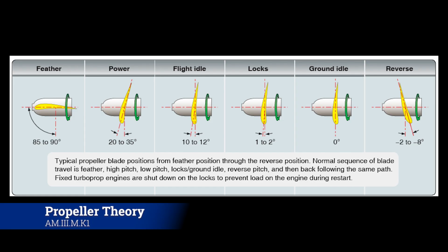C-130s are another really good one to watch. You can watch videos of these guys landing, and as soon as it hits the ground, you'll hear the engine sound, or the propeller sound, change drastically. That change in pitch is those props going into beta, and it'll also go wah, because it's now fighting against the relative wind of the plane, causing it to slow down and ultimately stop.